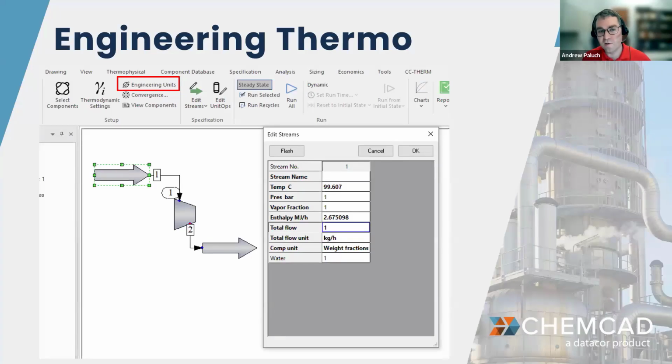Well, when we talk about balances in open systems and open flow devices, we can then jump over to CHEMCAD and demonstrate to students how we can model a compressor. So let's look at a simple example of modeling the adiabatic compression of steam. The spreadsheet is incredibly simple, but we can demonstrate how to perform the calculation. We have this process simulator which can perform this calculation, but we can also draw some interesting comparisons to how we solve these by hand in class.